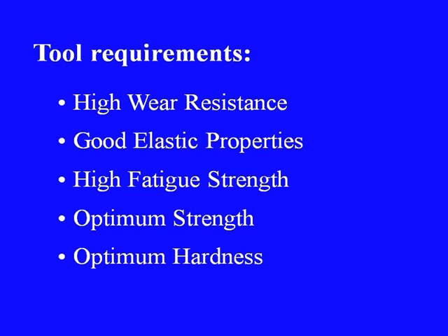Mass of the tool should be minimum possible so that it does not absorb the ultrasonic energy. Then what are the other requirements of the tool? It should have high wear resistance, good elastic properties, and high fatigue strength as it will be continuously subjected to fatigue kind of loading under very high frequency.